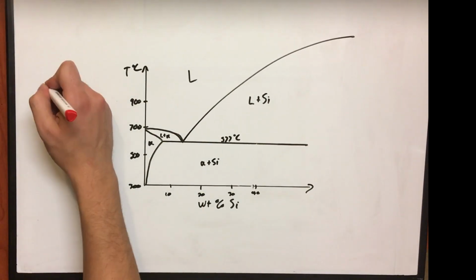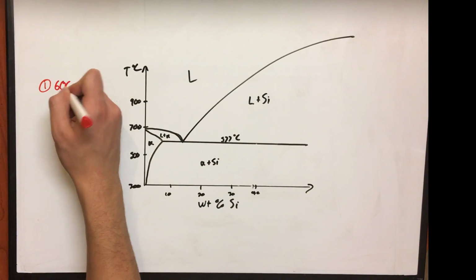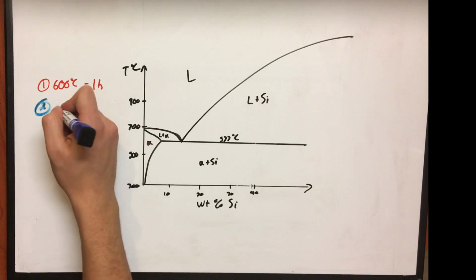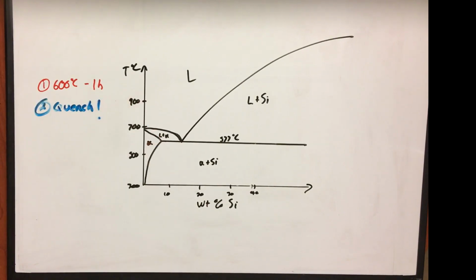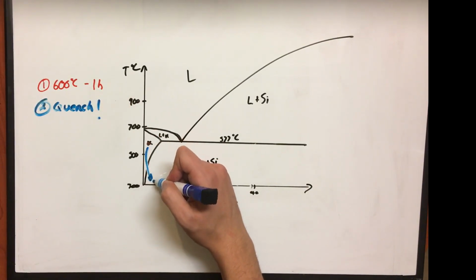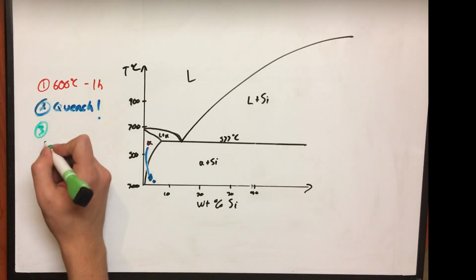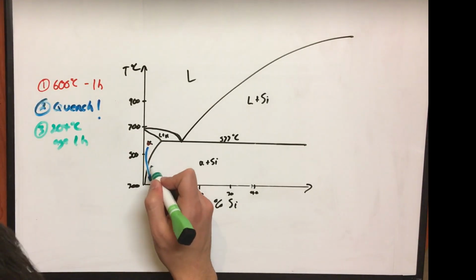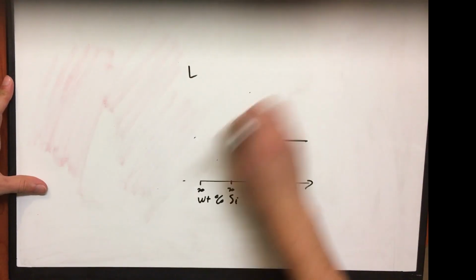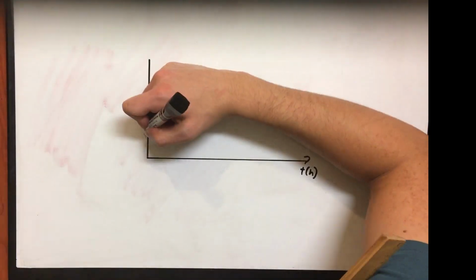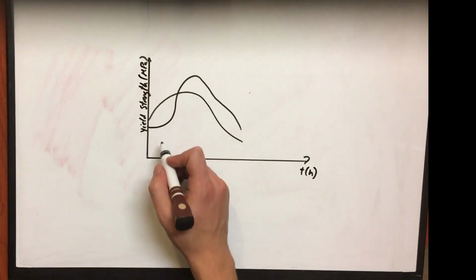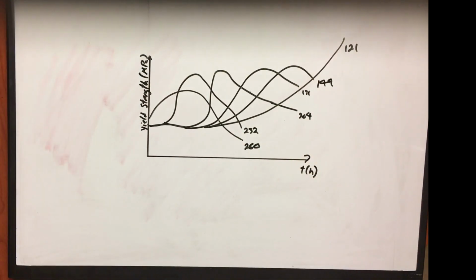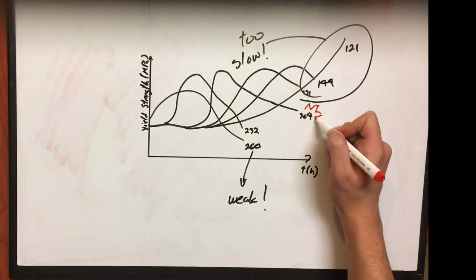the stem in a furnace up to 600 degrees Celsius for 1 hour until the alloy is in the alpha phase. This is followed by immediate quenching to freeze the structure in this phase. We then raise the temperature of this material up to 204 degrees Celsius and hold it there for 1 hour to reach peak aging. Unfortunately, higher yield strengths cannot be obtained realistically since the longer transformation time is not feasible for large scales of products, which will bottleneck the manufacturing process.